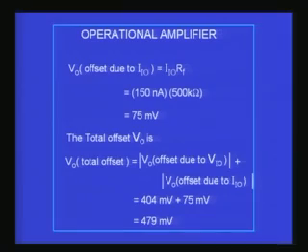So, you can see that by knowing a very simple relationship between the output and the input, in these cases one can actually measure input offset voltage, measure input bias currents also, and calculate the contribution to the output offset voltage from these two sources.